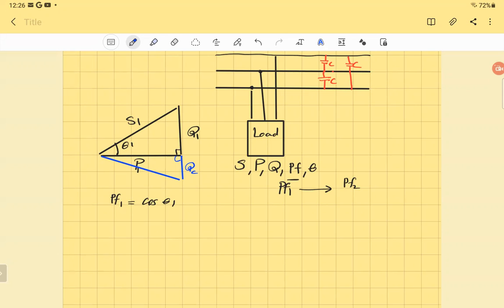Do you have an idea why the power is constant, doesn't change? If you add the capacitor, it only affects the reactive power, does not affect the power. Why do you think? Or do you think it should affect the power? It shouldn't. Just say whatever you expect. The first question, do you think the capacitor should change the power? Yes? Why? Because it's allowing more current to pass, so you would think there'd be less current and voltage coming at the same time. Okay, but there is something.